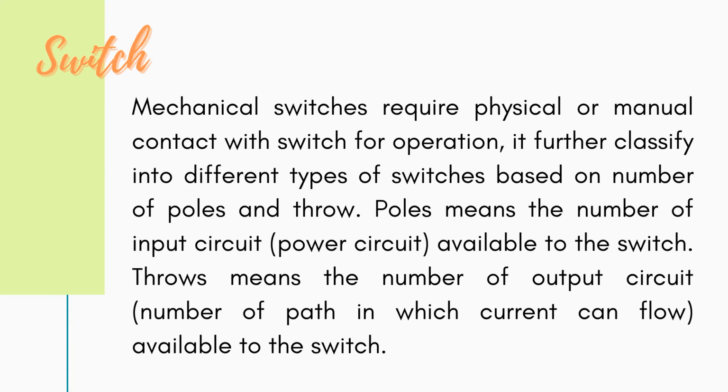It is further classified into different types of switches based on number of poles and throw. Poles means the number of input circuits, power circuits, available to the switch. Throws means the number of output circuits, the number of paths in which current can flow, available to the switch.